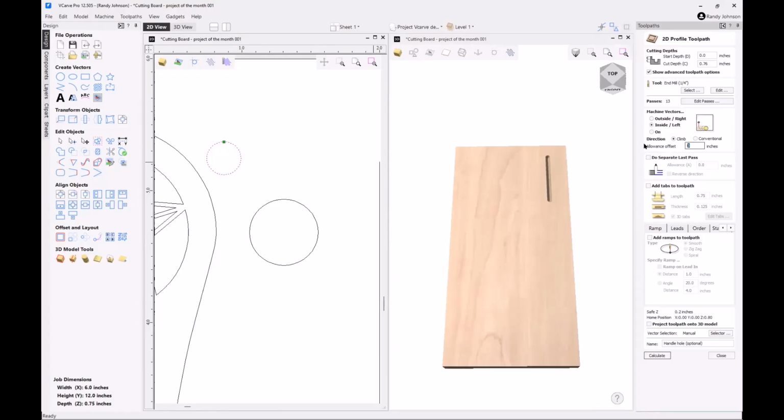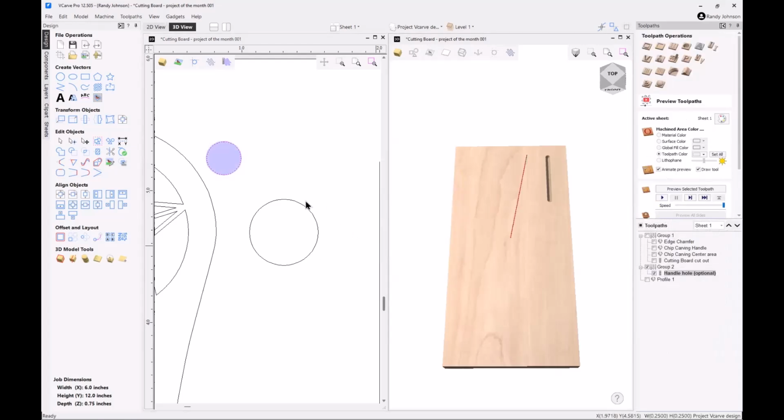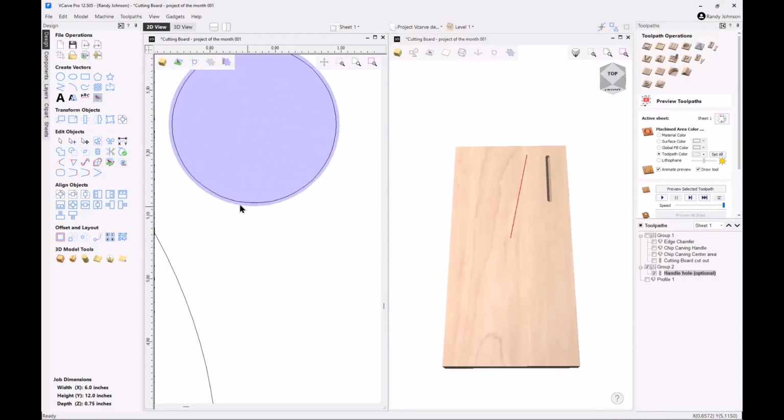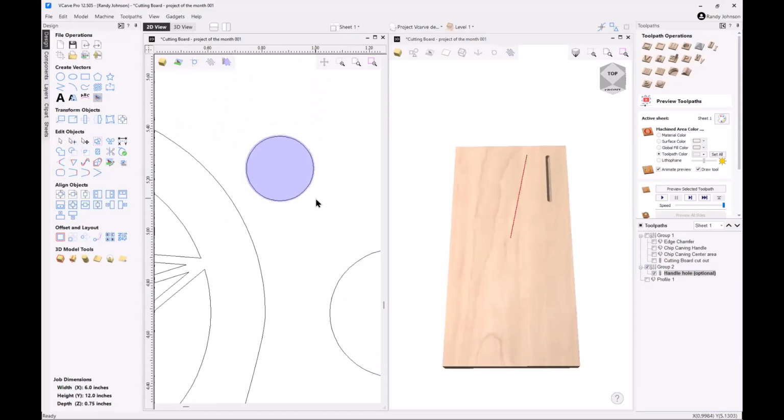So we'll go ahead back up here to that allowance. We want to make the hole a little bigger, so we actually have to add a negative allowance. So we'll just add a paper thickness all around, because when we double those, that'll be 0.01, which will give us that 0.26 when we're done. And bingo, it went in that time, and there you can see a little extra cut.